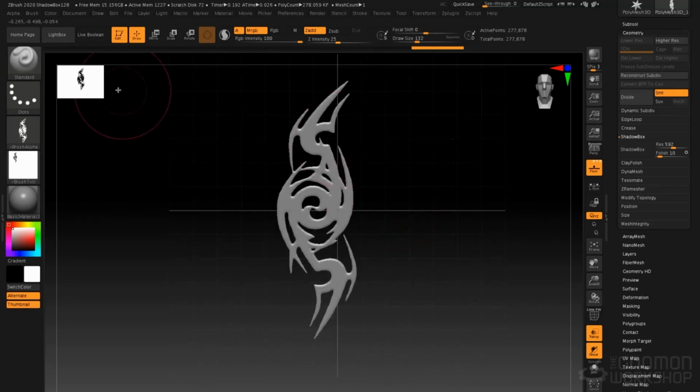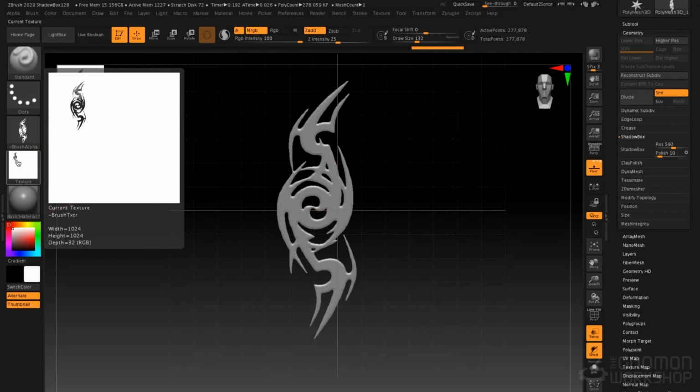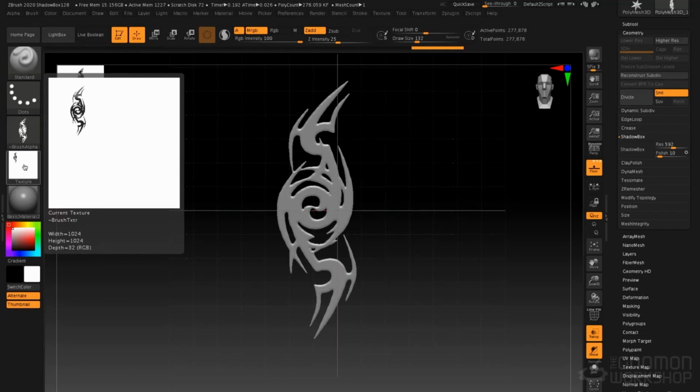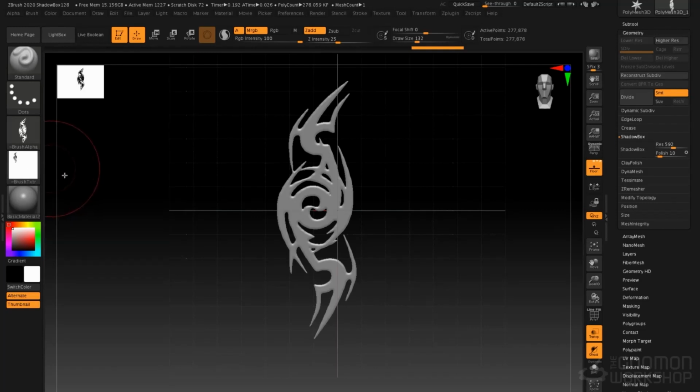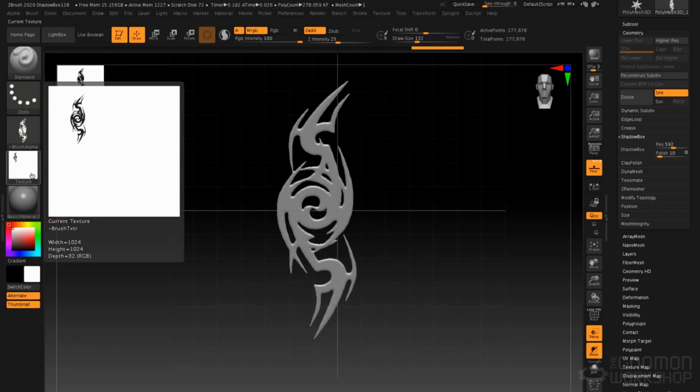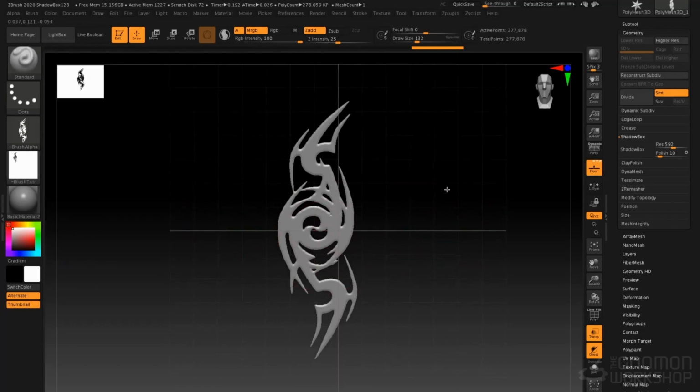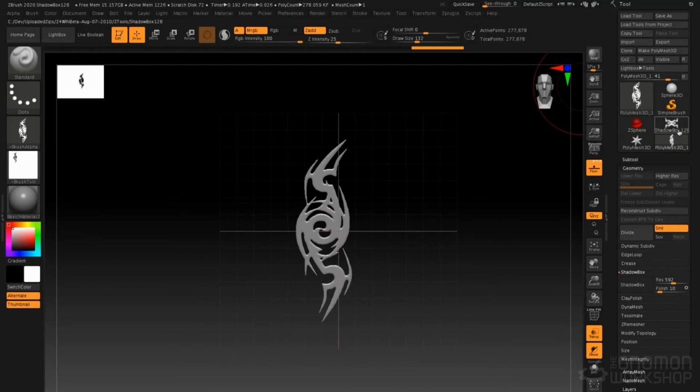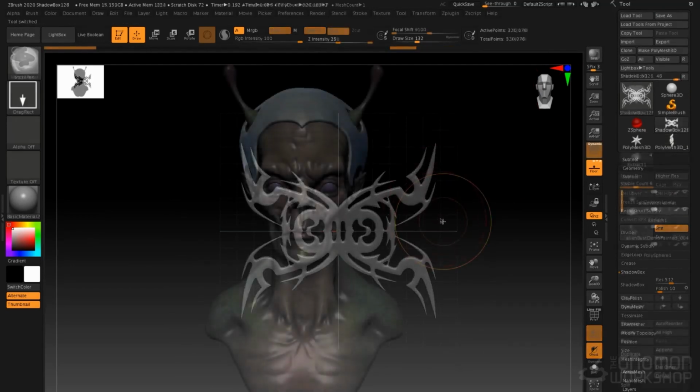So any black and white image that you can load into Photoshop and paste into that guide template, you can use to establish your shapes. So if you have profiles drawn on your item, you can load those up like front, side, top views. You can load those up and then generate your mesh based on those profile silhouettes just by masking by intensity. So let's take a look at how we can use this shape in an interesting way.